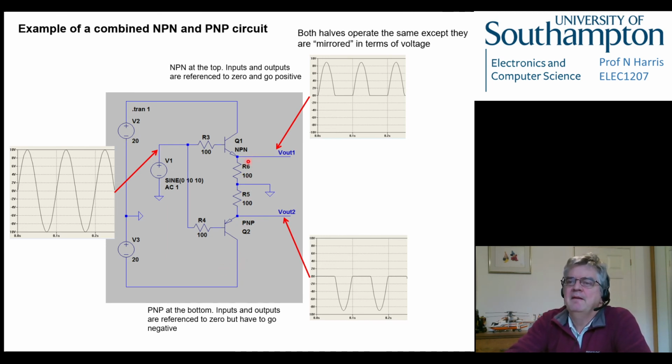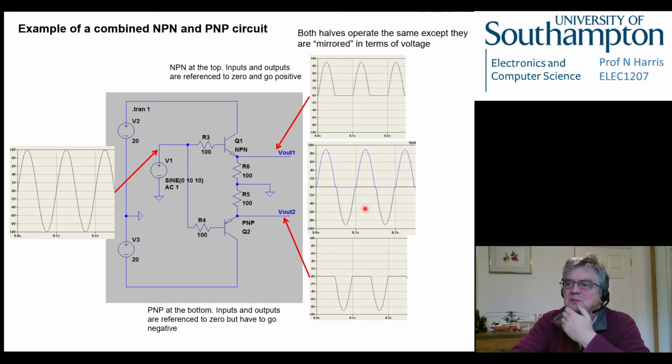In this case we've got an amplifier, with a sine wave coming in based around 0, so there's equal up and down coming in. It's being amplified by this circuit here, but in this case we're only seeing the positive half of the cycle, because that's the nature of these transistors. They can't conduct current in the wrong direction. And in this one it's the opposite, and we're just seeing the negative pulses, and then we can combine them together, additive in the middle, and we can add these two together to give us the combined version.